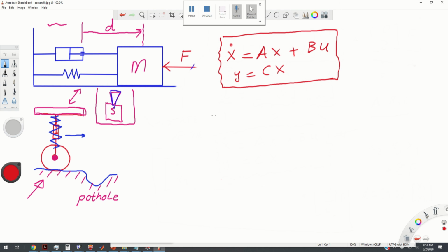So our next step is to represent such a state-space model in a discrete time domain. Now, there are several methods to discretize such a system. One of the basic methods is to use backward or forward Euler method. So if you use the forward Euler method, you can approximate the first derivative as follows.